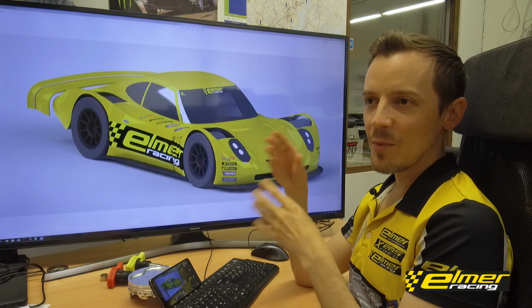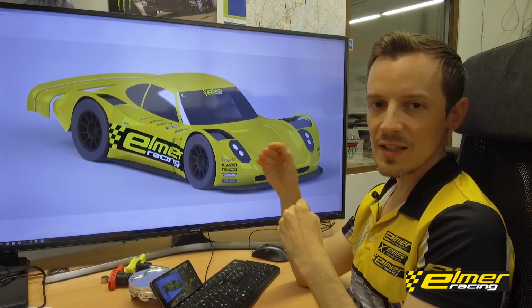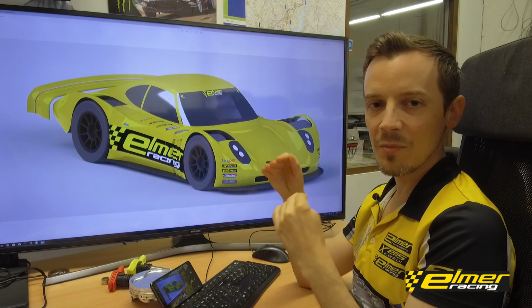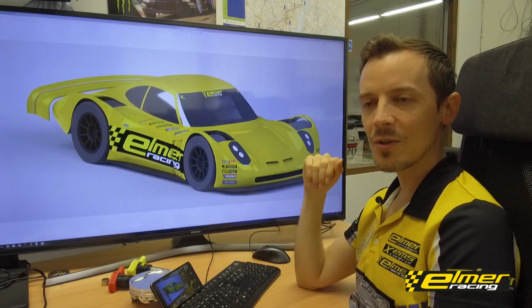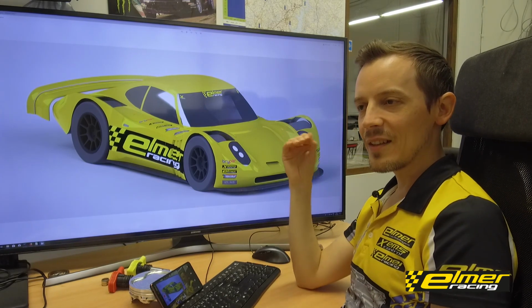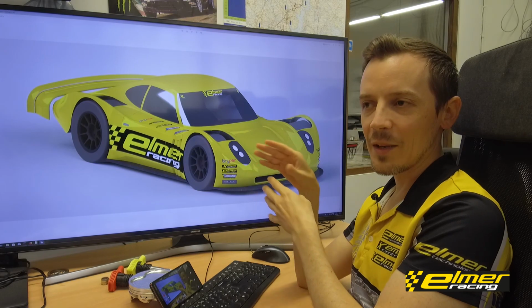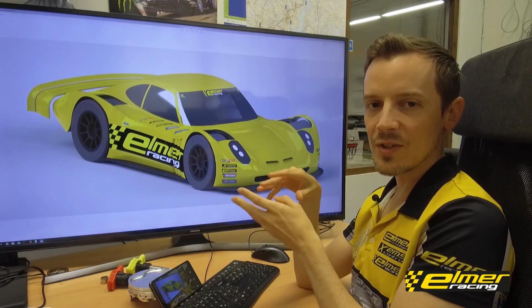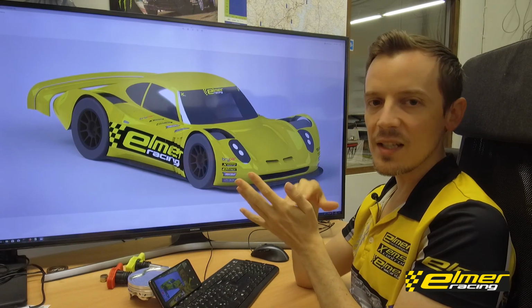So you end up with the problem that you can't really use air anymore, or you have to limit your testing speeds so that you're below the speeds where the Mach number starts affecting the airflow too much. So even in wind tunnel testing you need to be aware of things and compare them, so that you're actually getting meaningful results. But in CFD it's even more difficult.